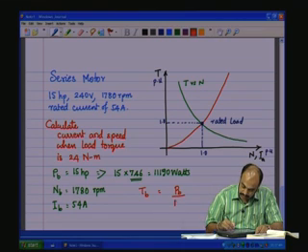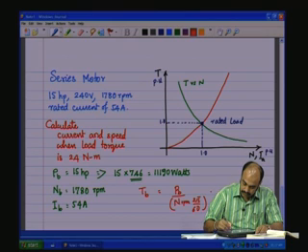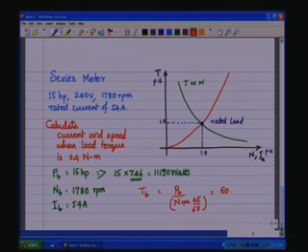But we have the speed in RPM, so n RPM into 2 pi by 60 would give radians. That is 60 into 11,190 watts divided by 2 pi into 1780 RPM, which is 60 Newton meter. This is the base torque, TB.